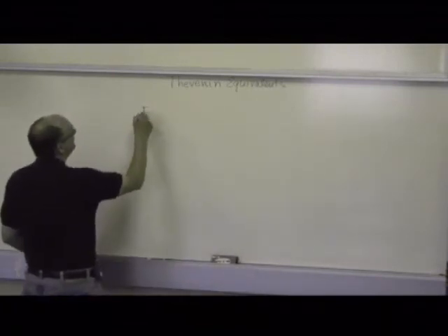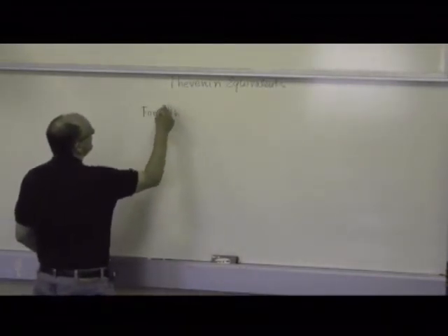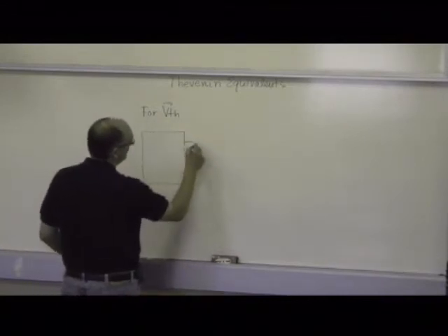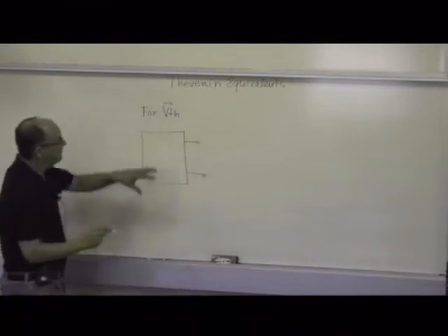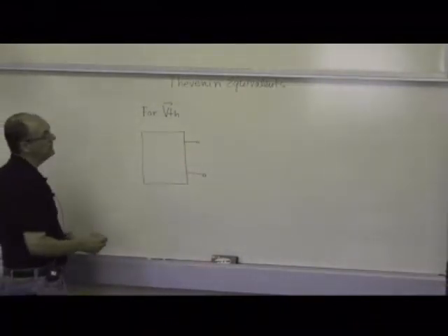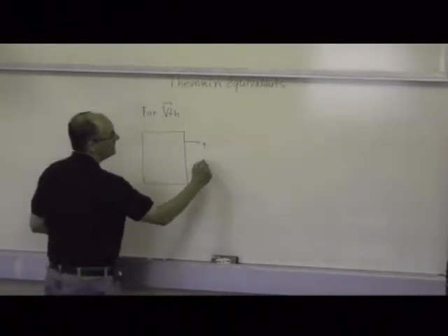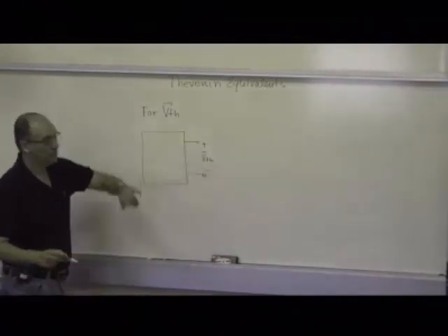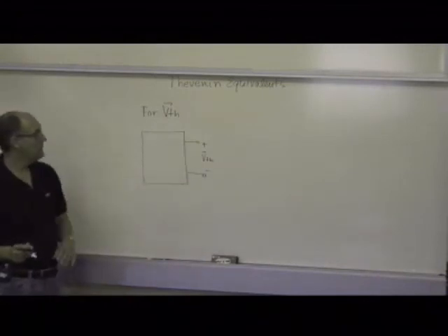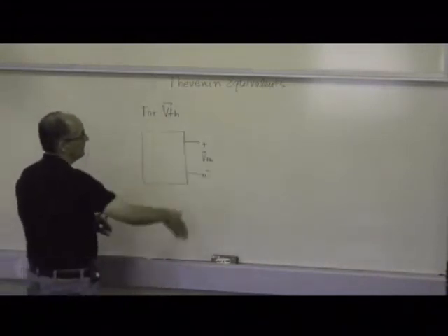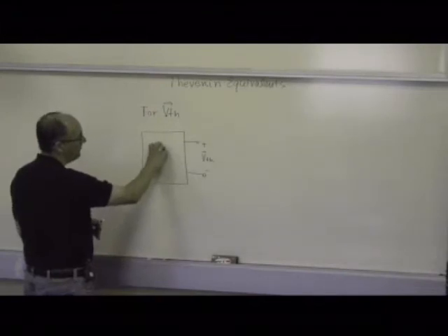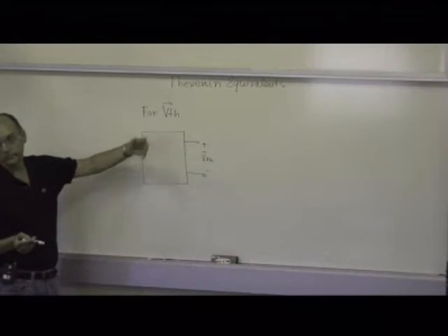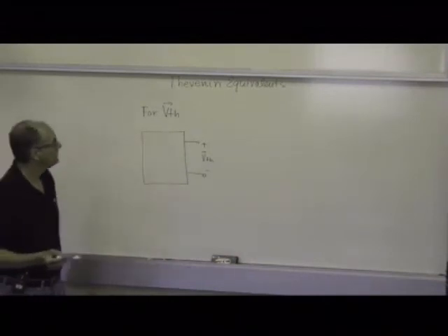For V Thevenin, what you need to do is basically disconnect whatever was hooked up to the part which you want to simplify, and simply calculate the voltage at these terminals, the so-called open circuit voltage. That's your V Thevenin. So basically take a pair of scissors, cut everything off, and solve what's left to find V Thevenin. That boils down to a no voltage problem, essentially.